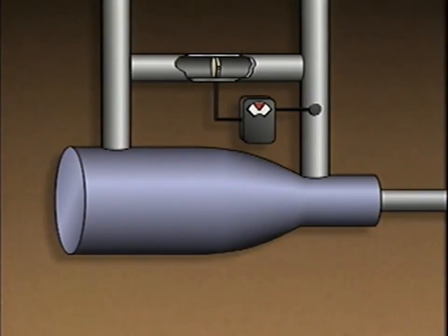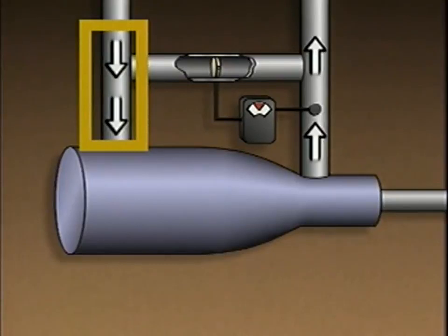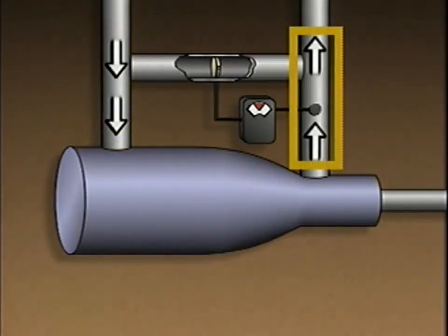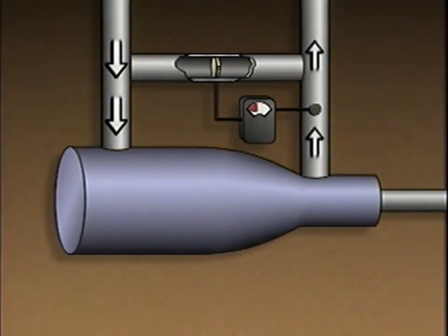The control system consists of a flow sensor in the compressor's discharge piping, a flow controller, and a recirculation valve that's located in a section of piping between the suction piping and the discharge piping. When low demand causes the gas flow rate to approach the surge point, the flow sensor sends a signal to the flow controller. The controller then opens the recirculation valve and routes a portion of the discharge gas flow back into the suction piping.